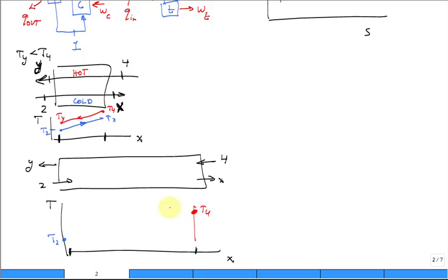But what you can find is that the slopes will be just like this, and the difference, delta T, will become smaller and smaller. If you have a short, stubby heat exchanger, not very much area, it'll be a large delta T within the heat exchanger.